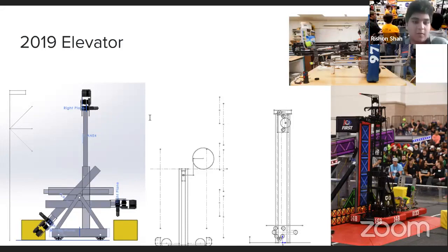Yeah, yeah. So, how do you guys deal with safety while prototyping, slash tips on prototyping safely? So on 971, we really put an emphasis on safety, just any time. You're not allowed to be in the lab without safety glasses. We have supervisors that have to be in the lab at all times. Anytime someone is in the lab, regardless of whether or not they're using tools, you need to let the supervisors know. If you're using any high-power machinery like the lathe or the router, and if you plan on cutting things outside, you have to let them know. Like really, safety is super important for us.